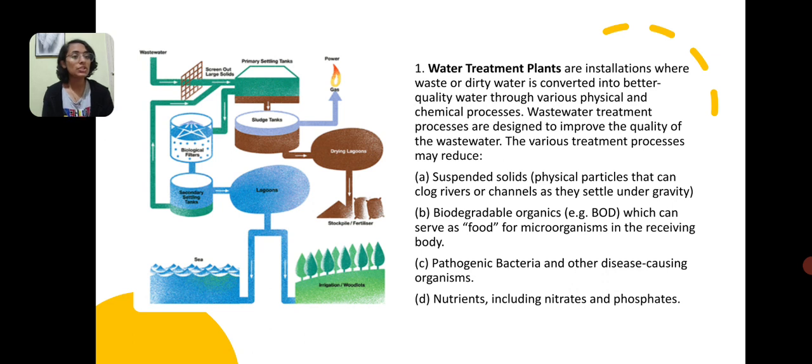The various treatment processes may reduce: first one, suspended solids; second one, biodegradable organics, which can serve as food for microorganisms in the receiving body; third one, pathogenic bacteria and other disease causing organisms; fourth one, nutrients including nitrates and phosphates.